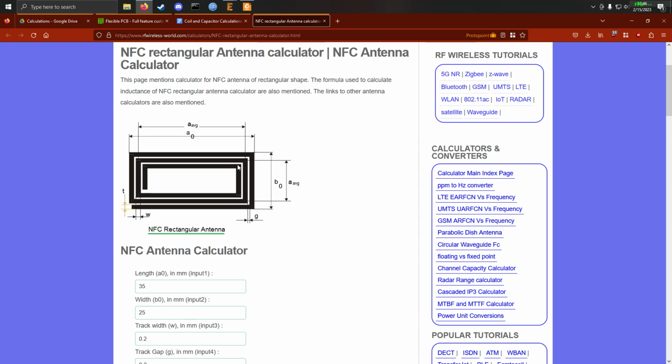It's very difficult to map out how much inductance you're going to get if you add coils on the bottom too. So for now, we're just going to mess with having one coil on the top of the PCB with a set number of turns. Or, in your case, it would be one coil of wire in a set size and just one layer of wire.